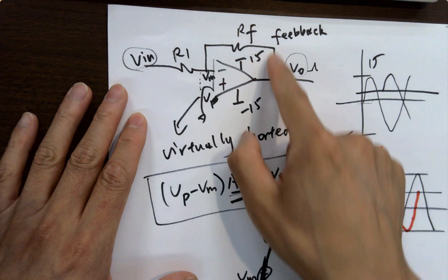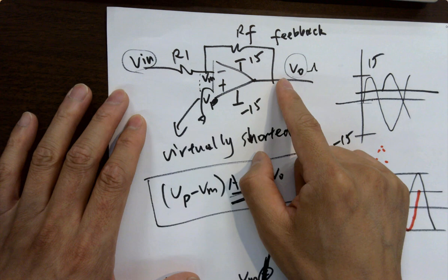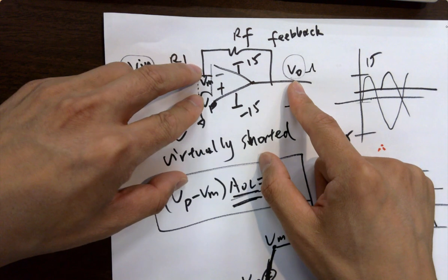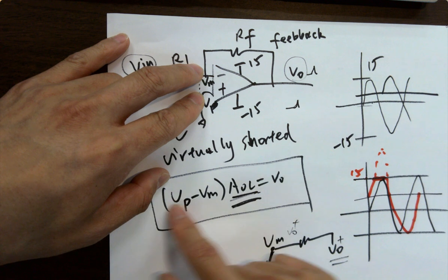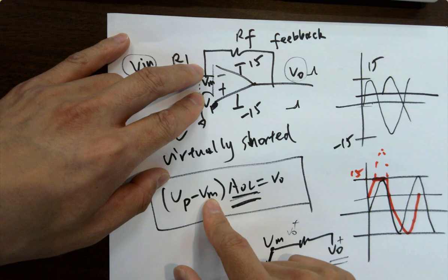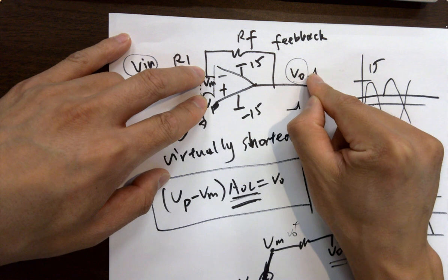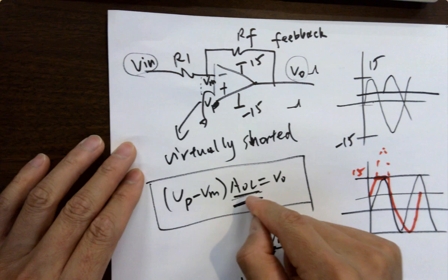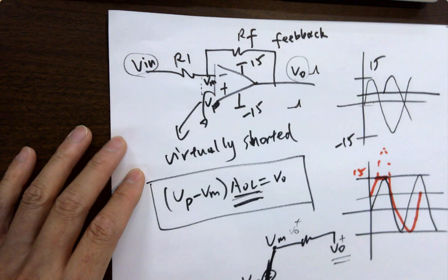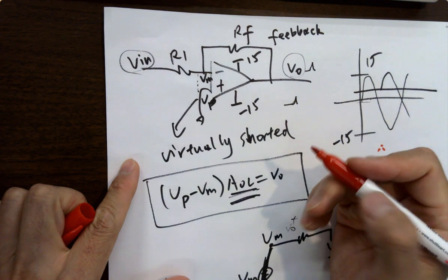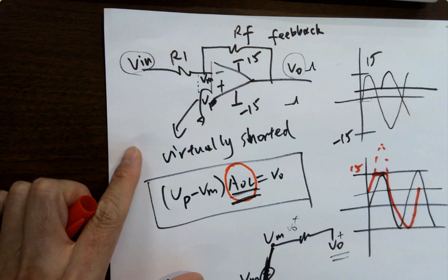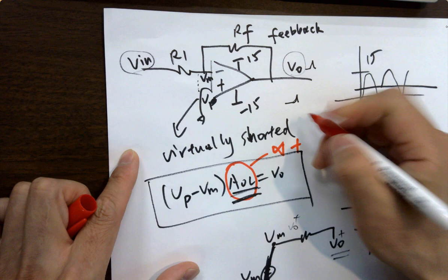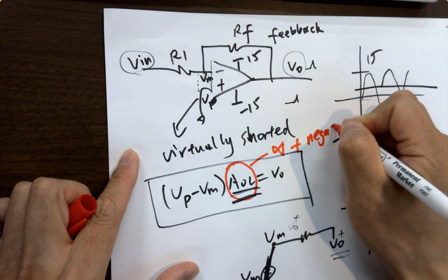But for the negative feedback mechanism over here, what you can tell is, for this part contributing to V out, if it is slightly larger than this, there will be a little pulse, but it's fed back and makes them equal. Because of this, it's always making these two equal. That's why, for an ideal op-amp, there is infinite open loop gain, and the feedback has to be negative feedback.